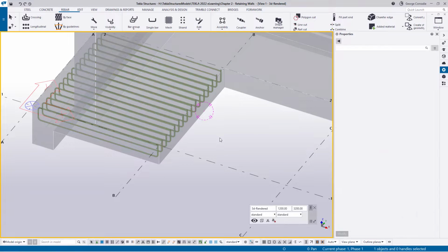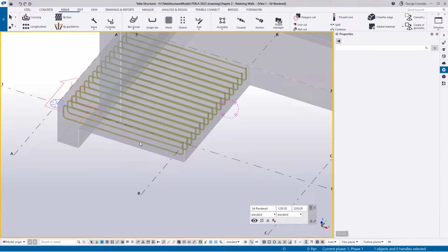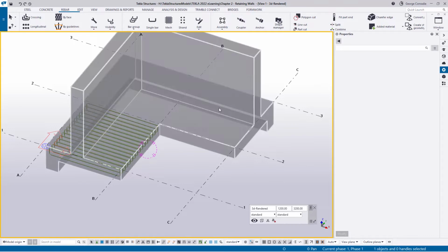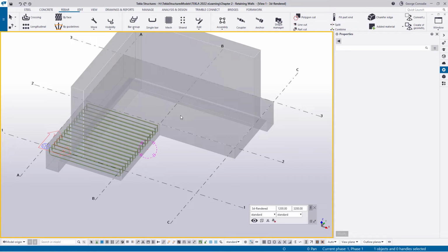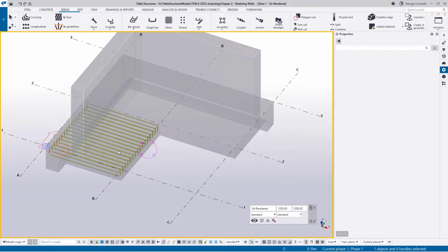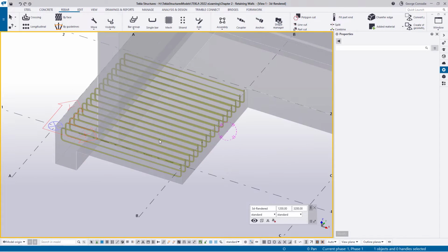And the reason for that is the engineer specified in this case that these bars are the dominant bars. In other words, they're in layer 1. And when we go around the corner of the retaining wall, those bars also have to be in layer 1 in this side. Now you can imagine if we had used the full thing, over here we're going to have a problem that our main bars are going to end up in the second layer rather than the first layer. So we'll stick with this method. So once I've got that, I'll finish off these bars before I move on to the others.